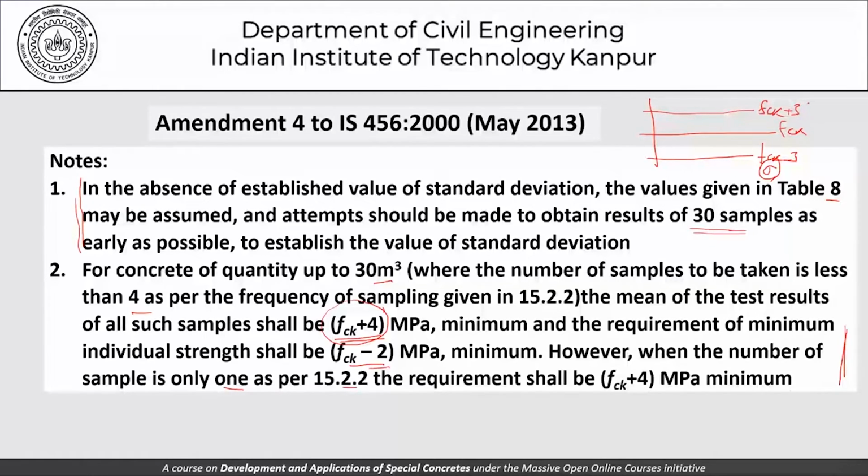So this is the kind of guidance that is available to us in IS 456 and perhaps other documents to guide us about acceptance of concrete. Now, this is something which as engineers we must try to understand very clearly, that the concrete mass has a certain mean strength. We are trying to evaluate it for acceptance, not for the mean strength, but from a characteristic strength standpoint.